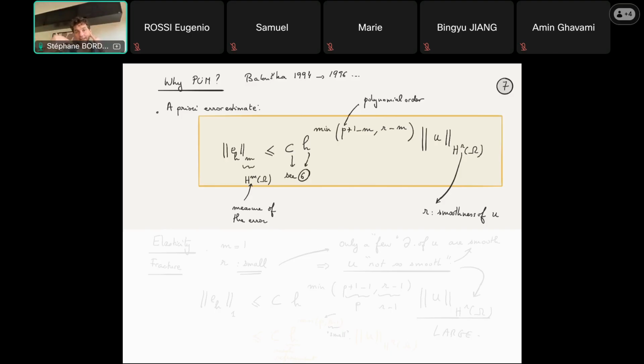Fortunately, this is why finite elements are the most widely used method by far compared to any other method. I mean, it's really like the panacea. It can solve almost everything. And why is that? I mean, of course, finite volumes, discontinuous Galerkin, for fluid flow problems where you have conservation laws, that's a different story. They are also very much used, especially in very high accuracy cases where you cannot afford to make any mistake, because finite elements do not conserve mass or volume exactly.